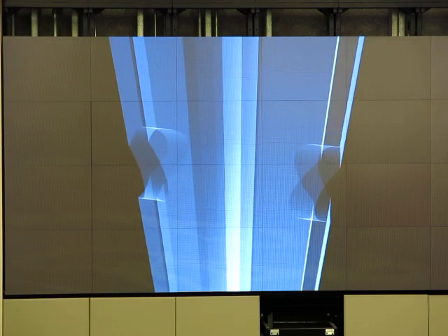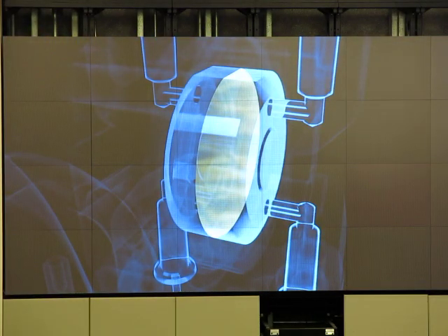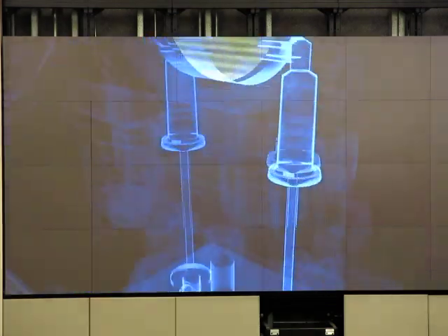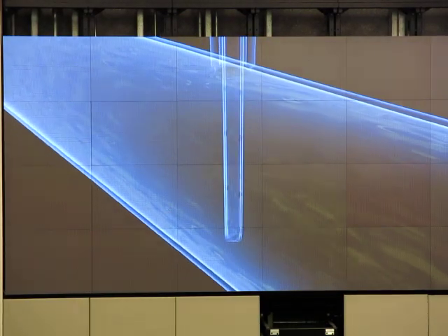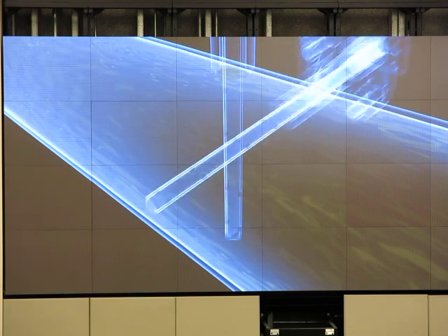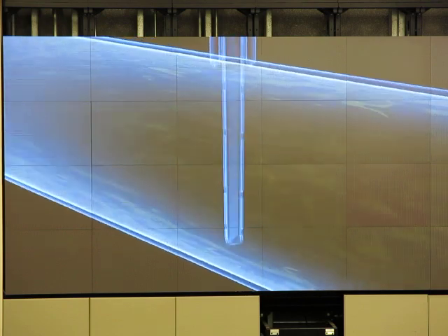Two separate tubes connect these holes to a differential pressure sensor. With its two pressure chambers, separated by a diaphragm, the tiniest pressure differences in the flowing fluid can be precisely measured. The individual pressure taps are distributed along the entire pipe cross-section to ensure a representative measurement. If there is strong interference in the flow profiles, it's advisable to fit a second Pitot tube, rotated by 90 degrees. If the fluid is not flowing, the pressure before and after the probe is essentially the same.